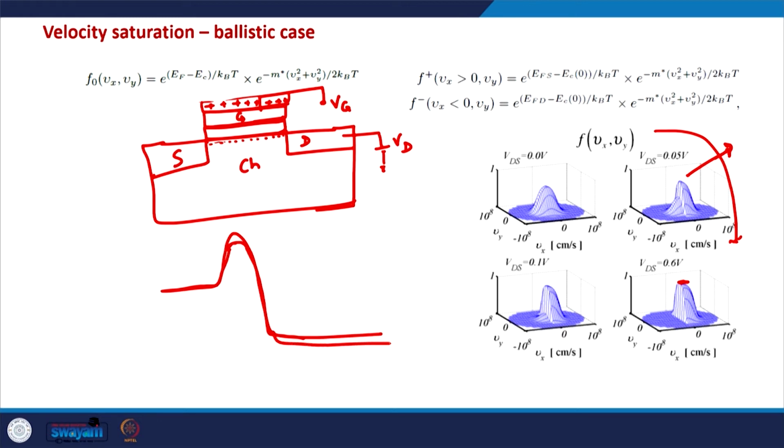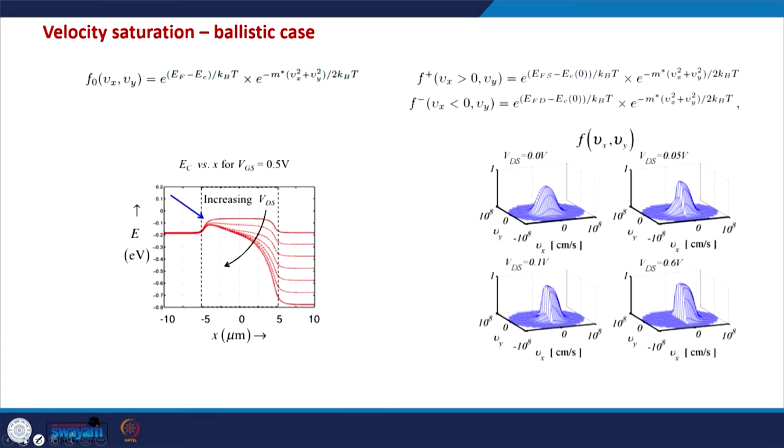of higher drain voltage. So a cleaner picture is shown here, as you can see that this is the source region, this is the drain region, this is the illustration of the barrier. Ideally this starting point of the barrier should not depend on the drain voltage, and it does not depend because that amounts to DIBL in the MOSFETs. But as we are increasing VDS, which means that this drain Fermi level is going down, the barrier is changing shape like this. Initially it was like this, then it becomes like this, and it becomes like this.